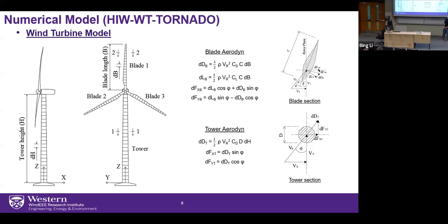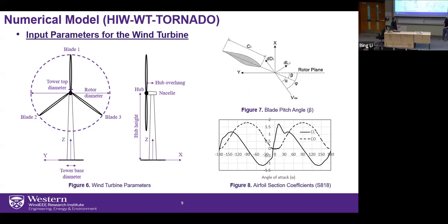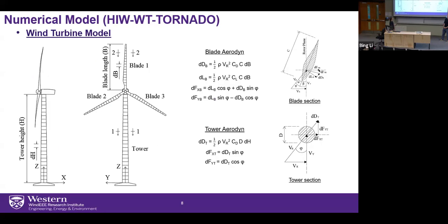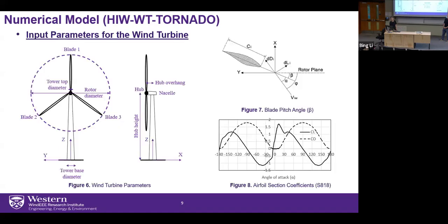This is the chord length, that's for the member itself. So basically, this is just a coefficient. It's changing from, I believe, almost -1 to positive 1.5. And if you want to get the forces, you have to get this coefficient that has no unit. This is related to each element of the wind turbine's blade component. These coefficients are actually from boundary layer winds, I'm not sure, because when they design the blade, they come with the blade. So we're not calculating those coefficients. So yeah.